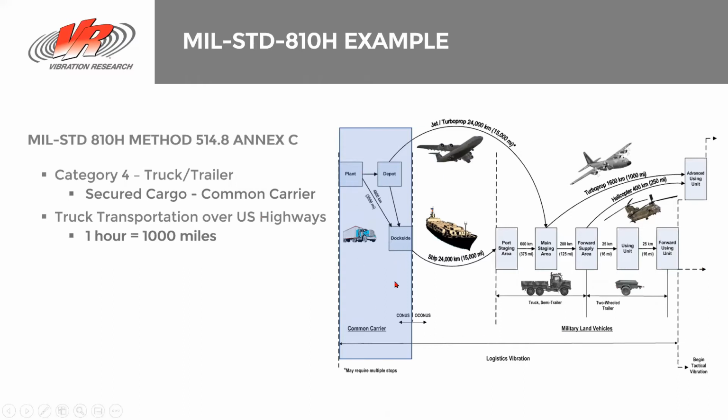But again, here, you can see what they've done is they've taken data from trucks that were driving all over the US in California, Florida, Chicago, New York, because there's different types of materials used in the road. There's different types of quality of road. And they took all that data together and they processed it into a random test and said, look, if you can pass this, you can survive those environments, right? The average of those environments.